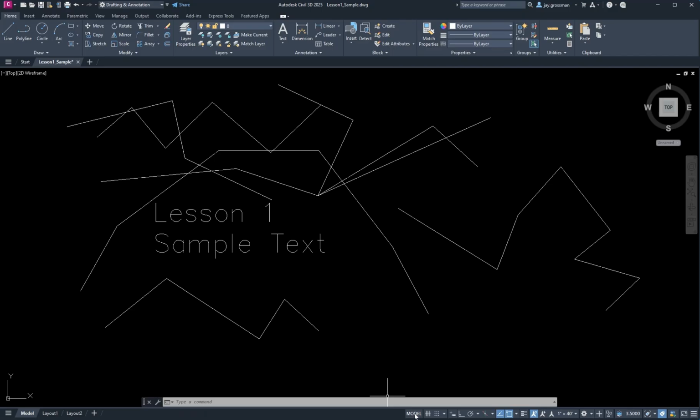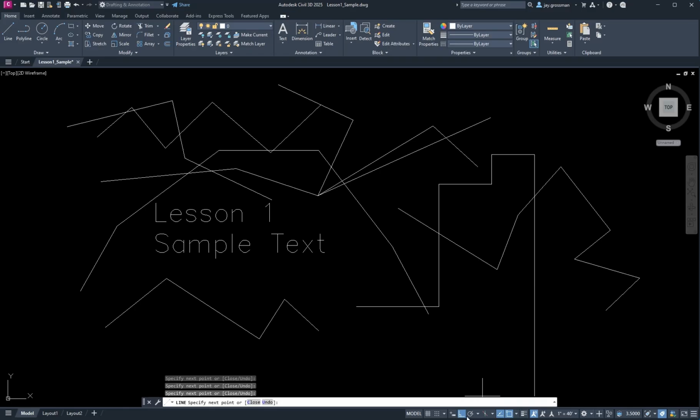And we've got, we're in model space, we're going to stay in there. And then we've also got ortho mode. And so if I turn on ortho mode and now I draw lines, now I cannot draw anything over here. I can't draw angles. I could snap to something, I guess, but I can only draw right angles. And that's what ortho mode is. It makes everything ortho rectangular, basically 90-degree angles from one thing to another. I can turn it off and I can complete my line, and I could do other options on that.